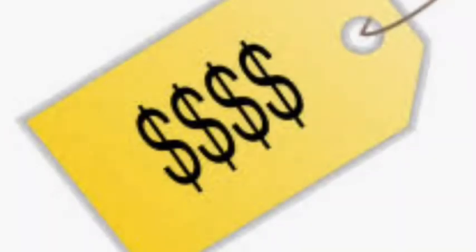Wind turbines under 100 kilowatts cost roughly $3,000 to $8,000 per kilowatt of capacity. A 10 kilowatt machine, which is roughly the size needed to power a large home, might have an installation cost of $50,000 to $80,000 or possibly even more. This is simply for private use, for example on someone's farm or at their home.